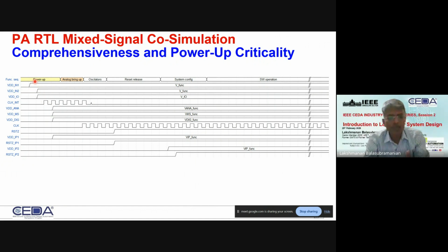They're all coming up. Once the primary supplies come up, the internal on-chip power management and oscillators start operating. There can be temporary low-accuracy, high-power oscillators that are used for timekeeping for a short period of time until the more accurate oscillators come up. And then multiple internal analog supplies, mixed-signal supplies, digital supplies, memory supplies, all of these on-chip supplies that I've shown in the block diagram, can come either together or in a sequence, right? They come at different voltage levels. Analog could be at 3 volts, mixed signal at 1.8, digital at 1.2 volts. And then the actual high-accuracy oscillators start to settle down and stabilize in their frequency.